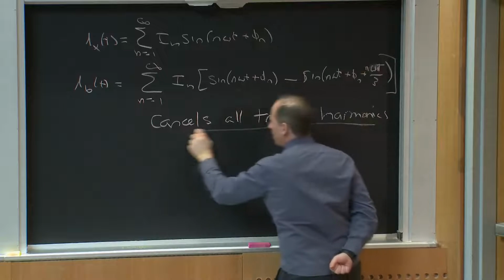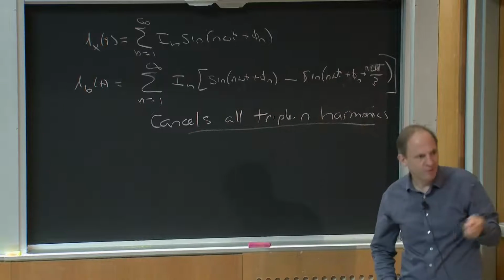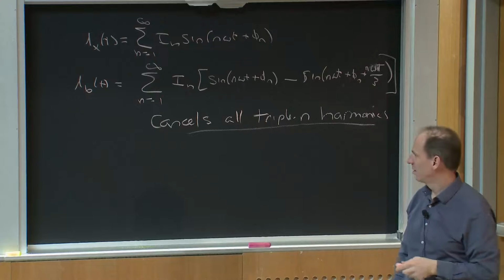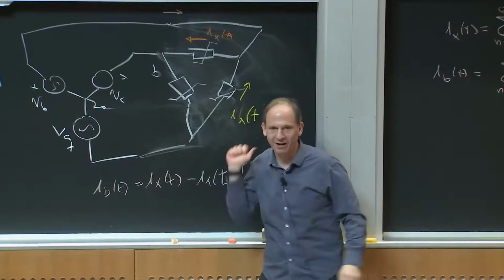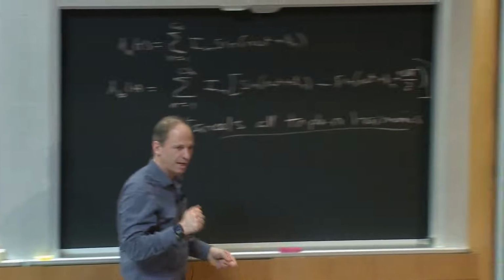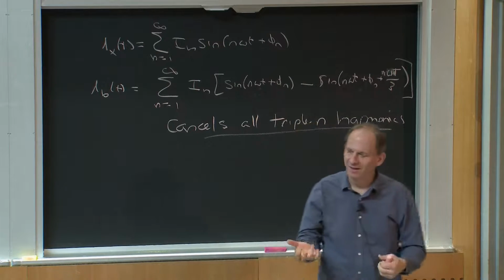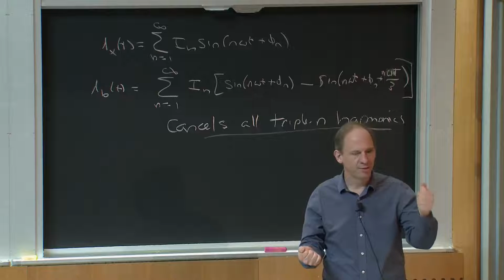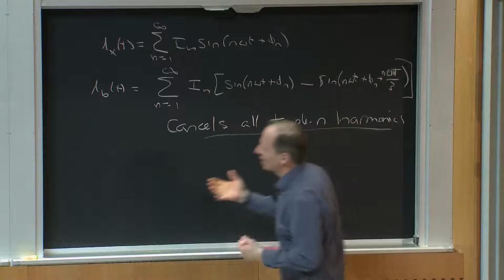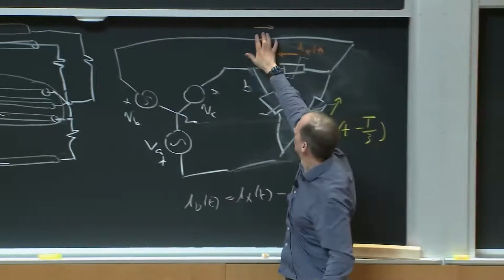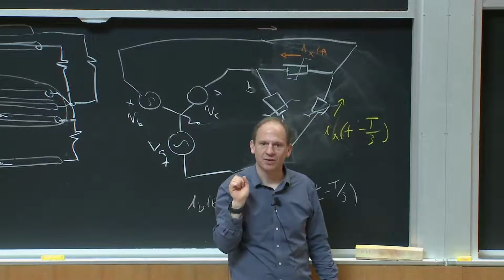Okay, so that means if I have half-wave symmetric waveforms, and that depends upon this nonlinearity, or the rectifier I use, I get no evens, and then I cancel 3 and 6 and 9, and then the lowest harmonic content I would have in the actual line waveform would be the 5th and the 7th.